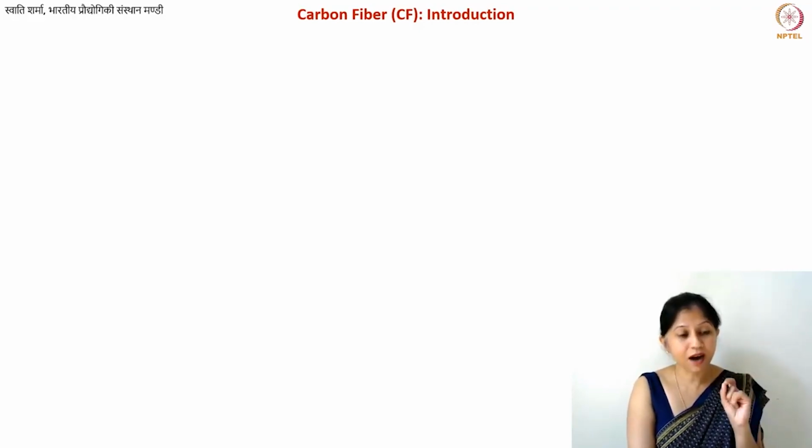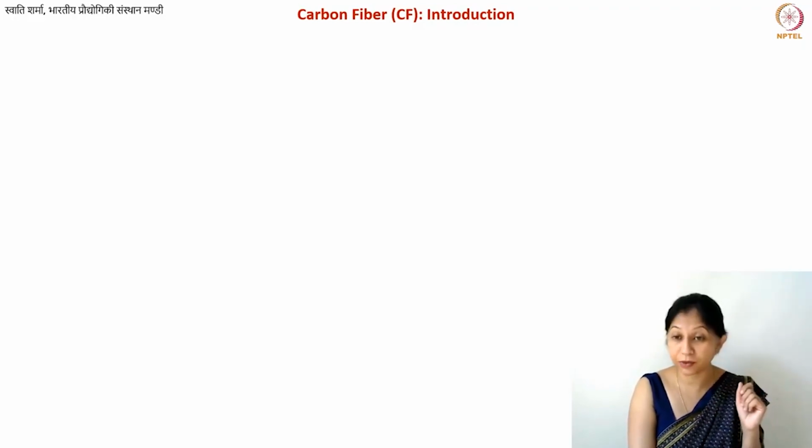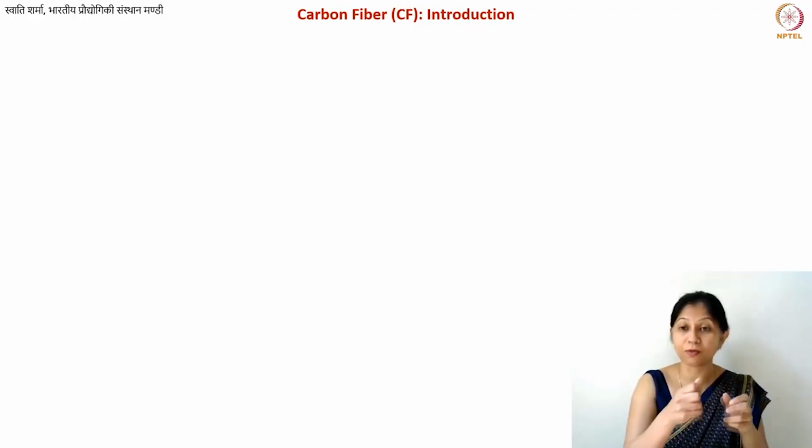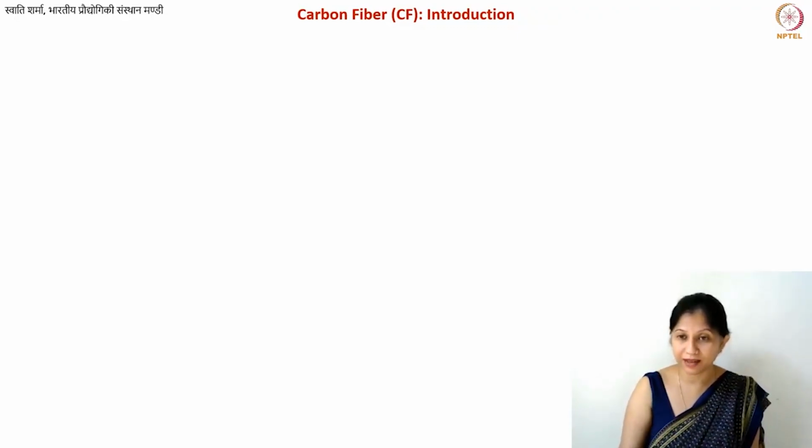You know that carbon fibers, when they are manufactured in bulk, because obviously you need a lot of fibers, you will perform braiding of these fibers, or what you will also do is weave cloth-like structures out of these fibers. Now these woven carbon fiber mats are used as sheets when we prepare laminates, and that is how we make composite materials. So these are prepared in bulk quantities, large scale applications, large scale structures.